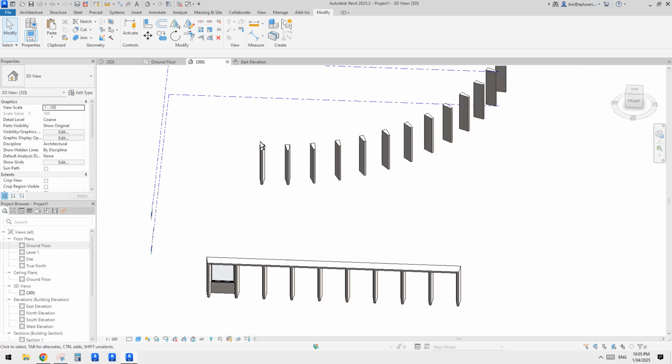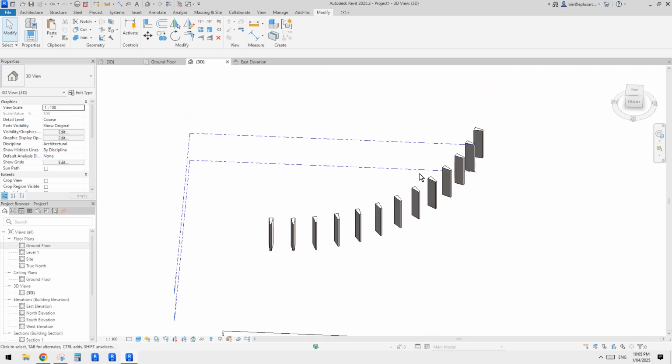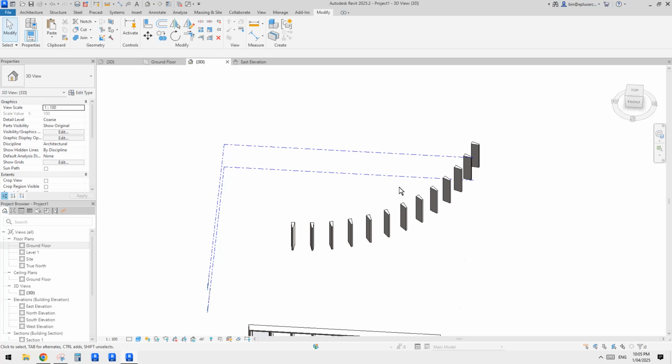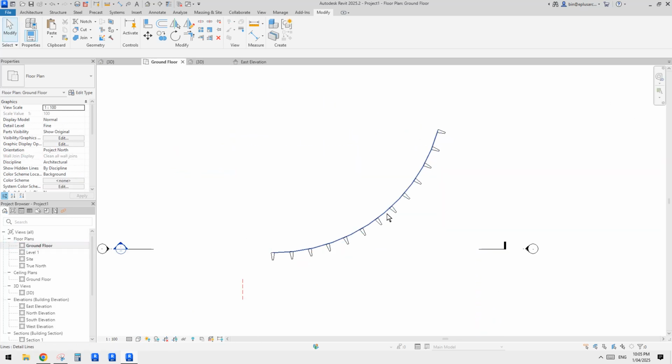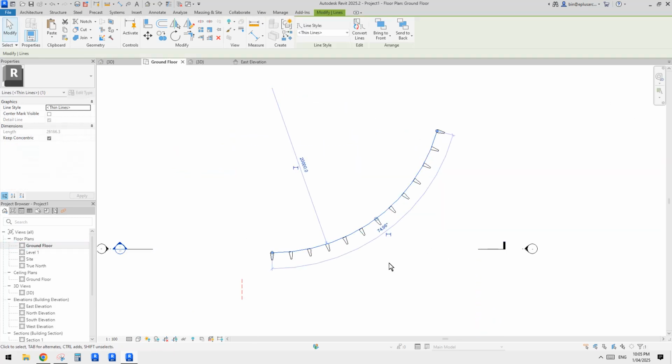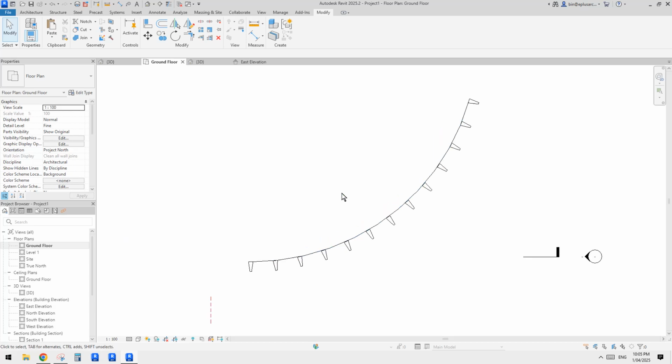Of course, this time we can't do extrusion, right? So it can be a sweep. It can be revolve, but usually I don't think revolve, it can be a little bit tricky because we also need to know the angle. I think sweep is easier for this one because we already have this detail line here. We can actually use this detail line as a path, and then we can just do a shape, a profile, right? So let's do it.